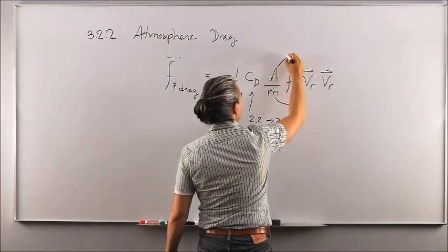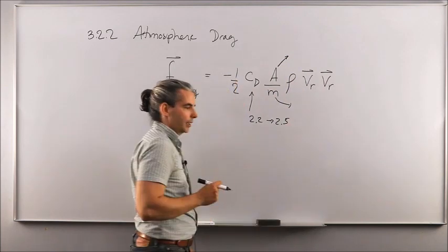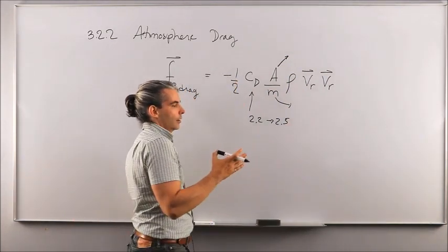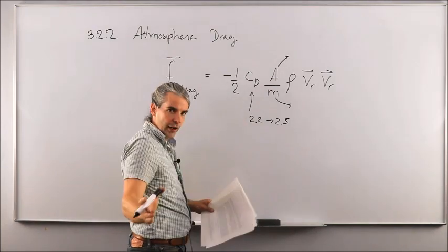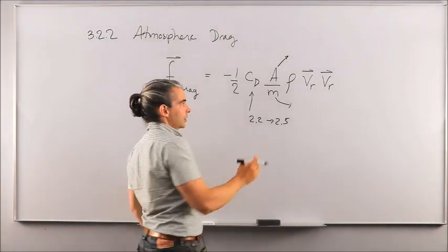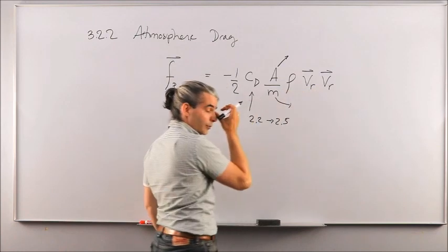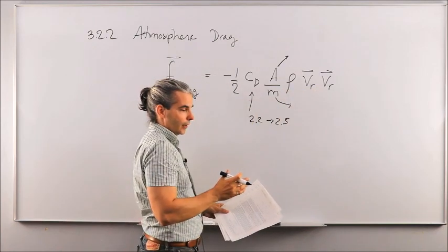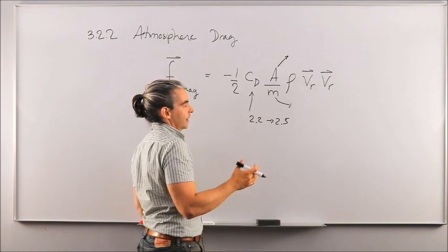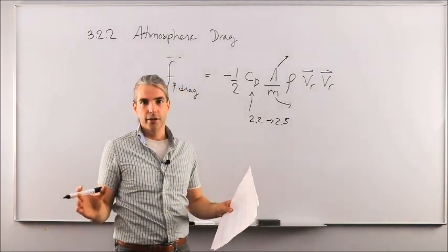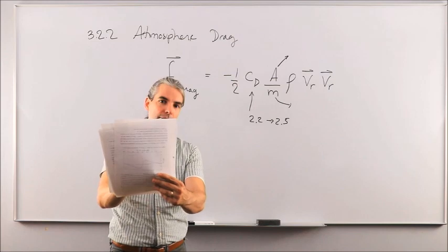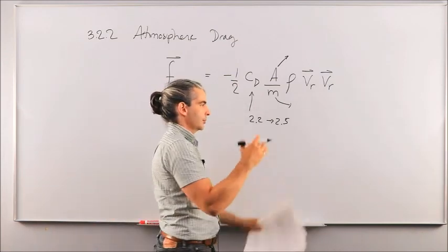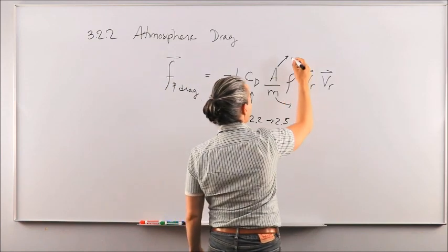The frontal area, you could either model it by taking the dot product of the normal vector for each face comprising the spacecraft with the velocity vector to then only compute the ones that are facing the flow, or you just pretend that the spacecraft is always oriented with one face only being exposed to the atmospheric drag effect.